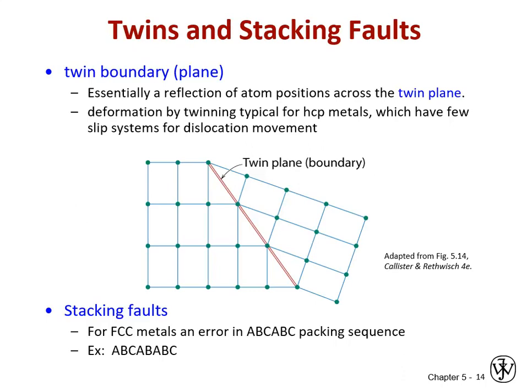Stacking faults, and this is picking up at the bottom of this slide, are when you have a stacking sequence error, and this is really specific to just our close packed systems, our hexagonal and face-centered cubic close packed. So if you remember, if you are building up in layers of close packed atoms to make a face-centered cubic or hexagonal close packed crystal, if you're going to make, say, a face-centered cubic, you would have atoms in positions A, then B, then C as you stack up to get a close packed 3D structure.